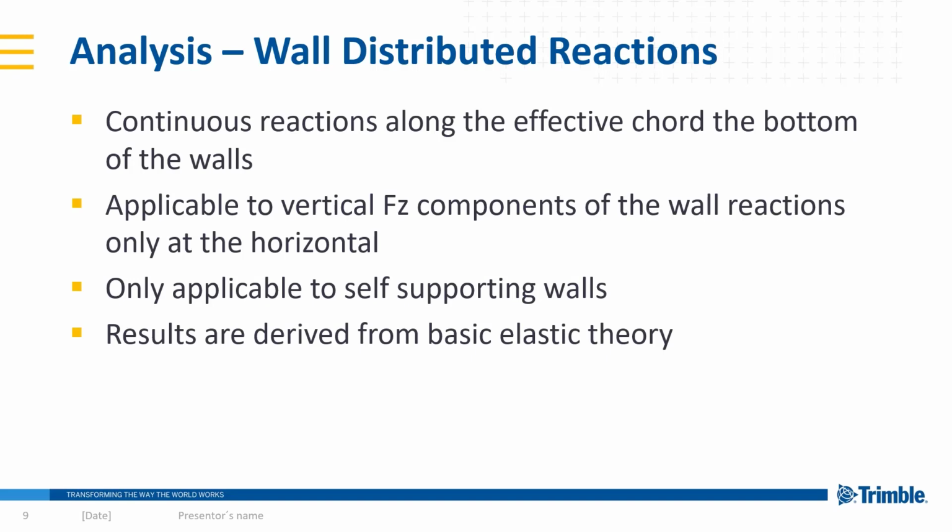This is only applicable to self-supporting walls. So if you have a wall supported by a transfer member or a raft or mat foundation, this won't apply. And the results are derived from basic elastic theory used to calculate the stress per unit length based on the total moment and vertical force acting at the centroid of the reaction line.